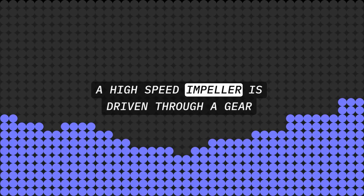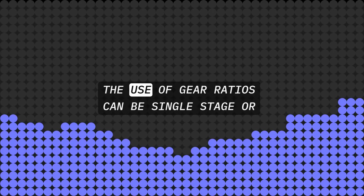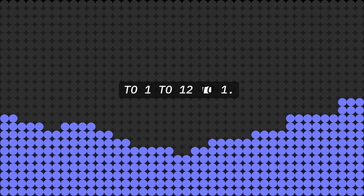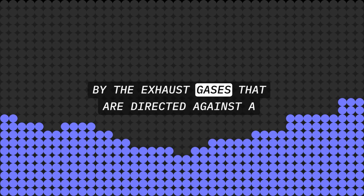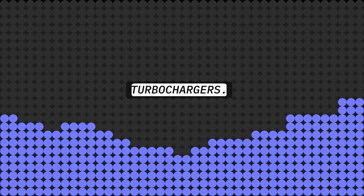A high-speed impeller is driven through a gear train from the crankshaft. The use of gear ratios can be single-stage or two-speed. A two-speed gear ratio normally varies from 16:1 to 12:1. Where does an externally driven supercharger get its power? By the exhaust gases that are directed against a turbine. For this reason, they are commonly called turbochargers.